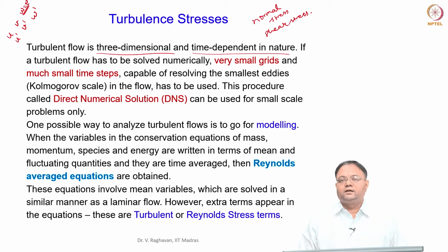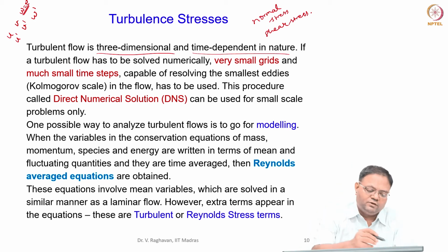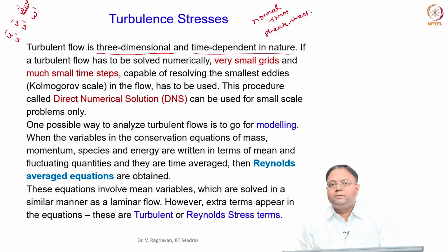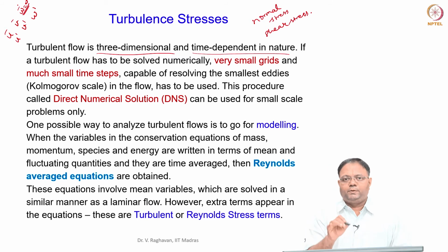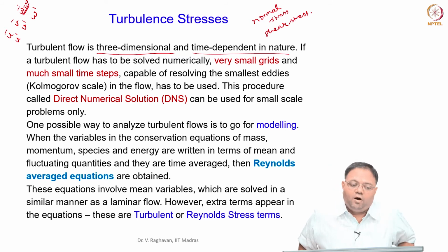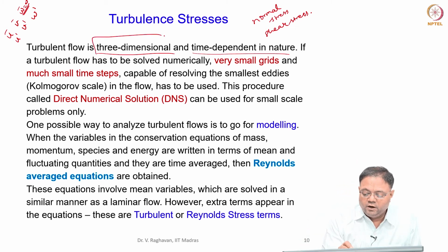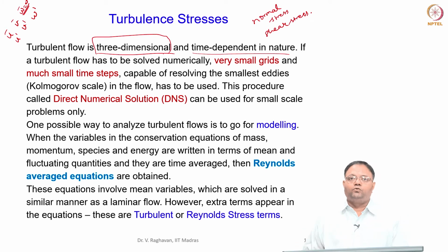So, that is the characteristics. You can see that in the third direction of the flow field there is no mean velocity. The mean velocity in the xy direction may be non-zero, but the mean velocity in the mutually perpendicular direction can be 0. However, the fluctuating quantity w dash may not be 0. So, that actually leaves the turbulent flow as a 3-dimensional flow.